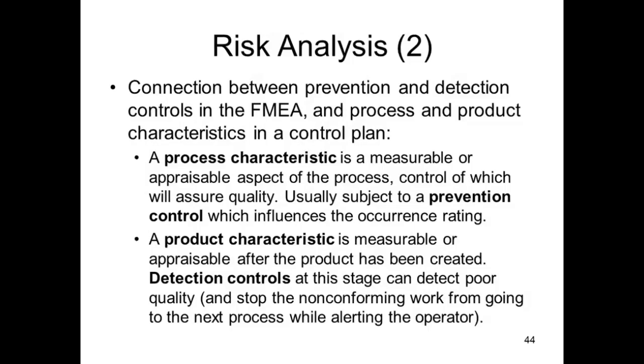I remember from semiconductor, we were supposed to etch a certain distance through a dielectric layer with either hydrofluoric acid or in some cases plasma, and they had an endpoint detector that actually showed when the dielectric had been penetrated by the etchant, and I think some additional time was added to make sure it was through completely. But that's an example of a feedback process control. It measures what the process is doing while it's doing it, and it prevents the problem from happening.